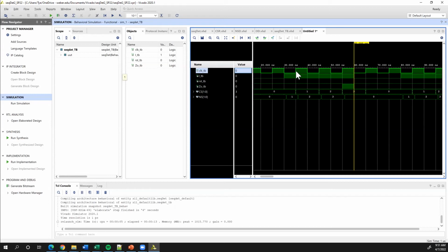Everything else, well, if I get a 1, 1, 1, I stay put, right? This state says I have a long sequence of 1s. I'll give them names as S0, S1, S2, S3. And then I say something along the lines of, well, if I get a 0 here, I stay put. If I get a 0 here, I go back. 0, I'm covered. 1, I'm stayed. Here, if I go 1, 1, 0, 0, I'm back. And if I go 1, 1, 0, 1, well, that's saying that I detected the 0 and then 1, 1. This state is that I've seen 1, 1. We come back to state 1.